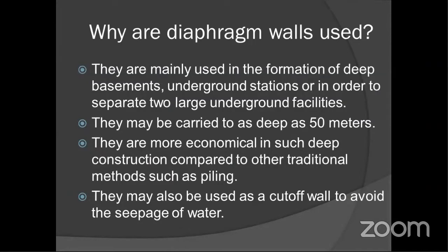So why are we going for diaphragm walls and not other construction methods? This is mainly used for underground constructions and for making the structure water retainable. And if we have minimum space area and have to utilize the maximum of it, under space constraints, we can use the maximum of the area where we are going to construct.